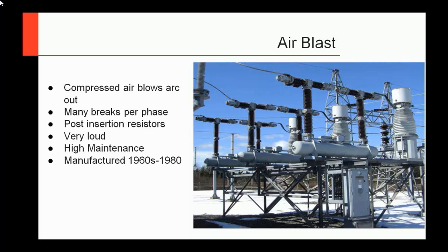They're very loud. When these things operate in the substation, you know it. I've seen cabinets blow out, just from the air not being properly vented out of the mechanism. Same thing, manufactured 1960s to 1980, no longer in production, as it was once again replaced by SF6 style. High maintenance, so these are once again being opted out and replaced with your SF6 circuit breakers.